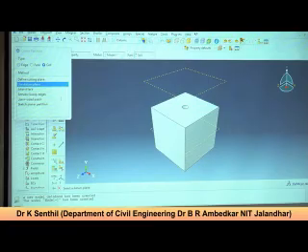So now I have selected it. The command is, select a datum plane. You see here this line you have to click. The color changes, right? Create partition. That's it. So now the top layer is clay and the bottom is whatever other different soil that you can define. Now this is one of the approaches.